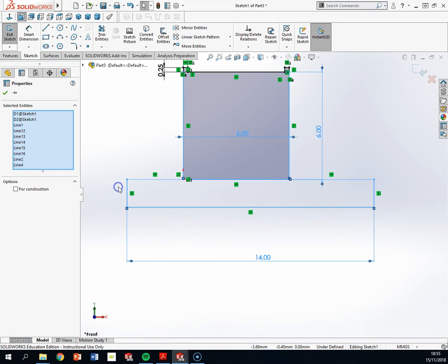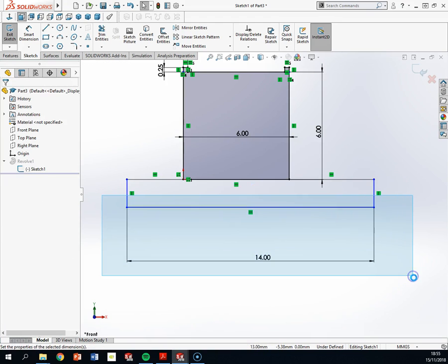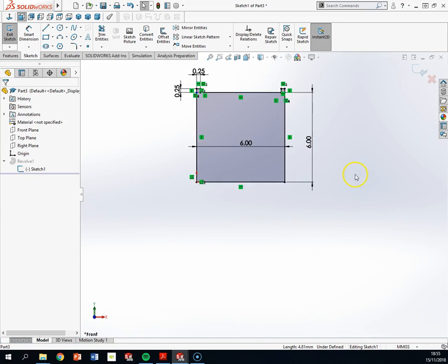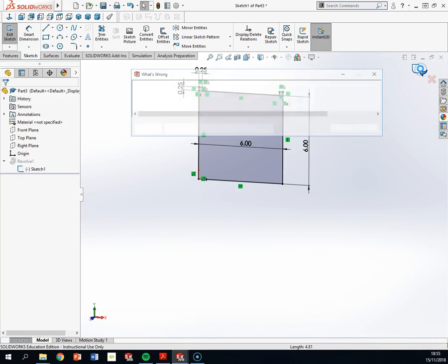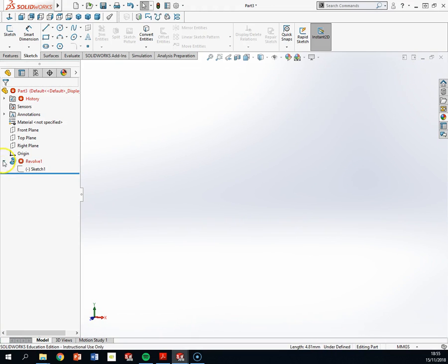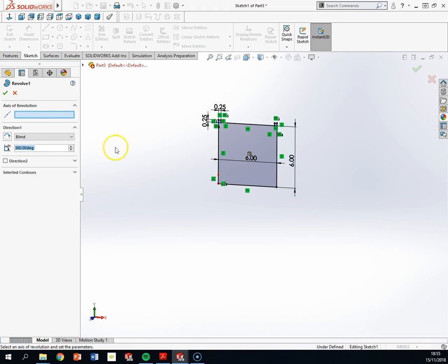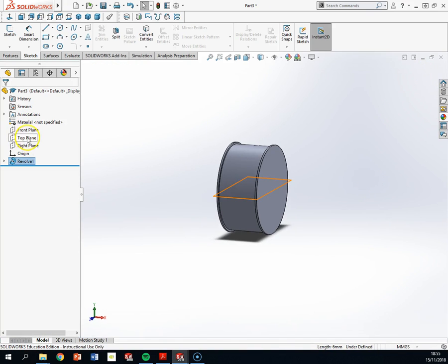okay, forget that. Let's try to be smart and do something a bit off the wall, but I'm going to take all these out. I'm just going to revolve it as normal, so it's going to have a solid center. And of course I got an error. That's great, brilliant. My axis of revolution now is going to be this one. That was the error. Now on the top plane, sorry, right plane,